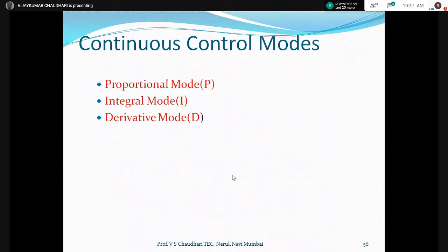So in such cases, if discontinuous control modes are used, the controller output will be oscillating, and the temperature or pressure or even the inlet flow of the chemical will not be accurately controlled. Then whether the output chemical product will be ethyl alcohol or not, we can't predict, because the process was not properly operating.